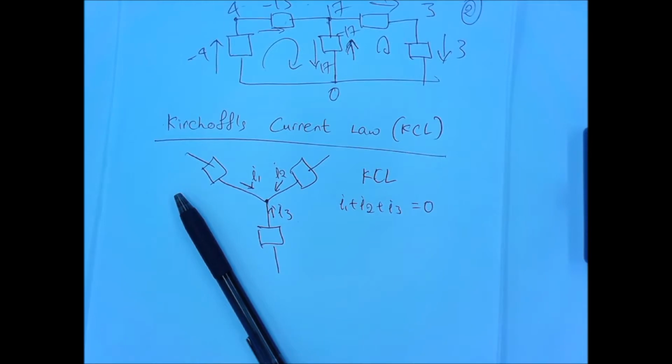Okay, so KCL is derived from actually stating that the charge is not being accumulated at any point in the circuit. Now, it's not saying it's impossible for that to happen. It is possible, but in the circuits we are analyzing, that's not happening. That's our assumption. Static charge can build somewhere in your circuit, in which case you cannot apply KCL. There are many cases where you cannot apply KCL because charge is accumulating inside something. But in our circuits, we'll assume charge is not accumulating.